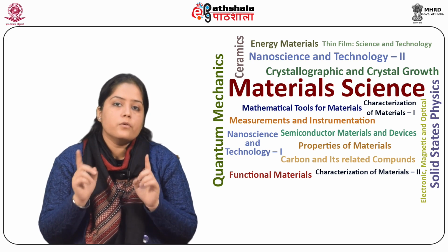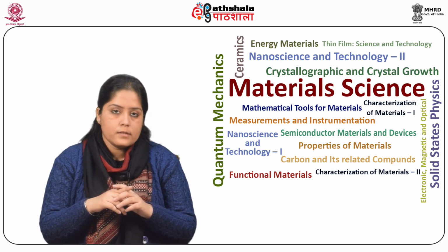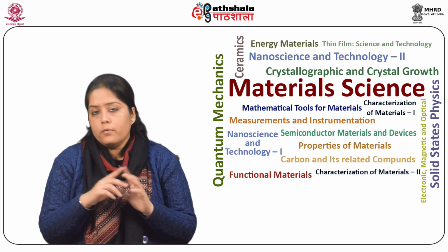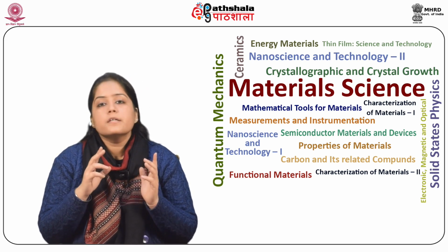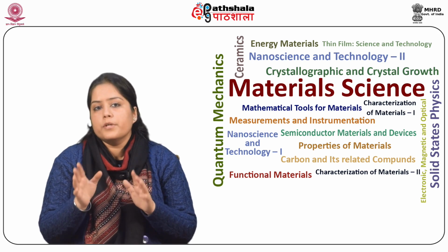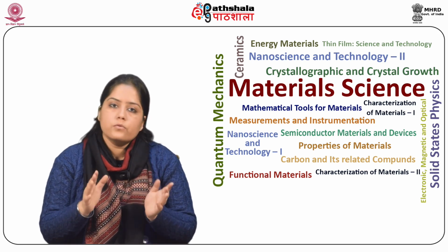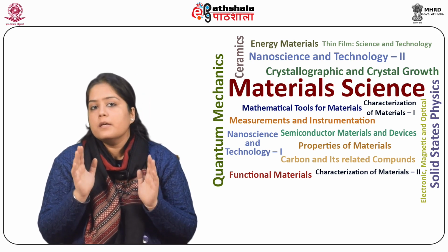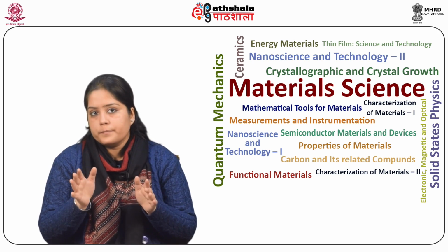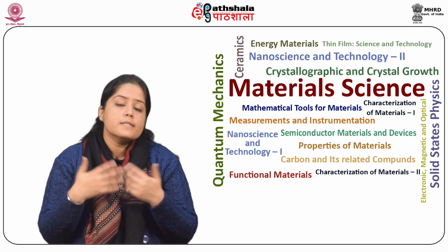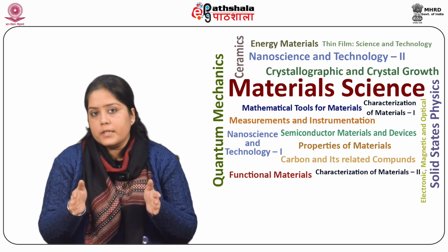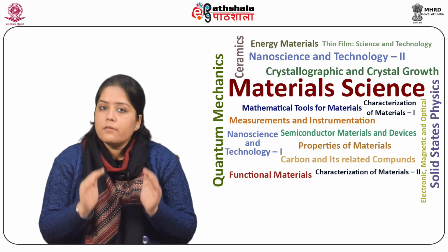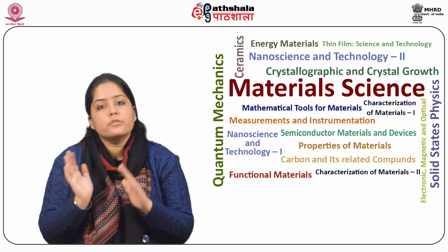The alloyed uranium such as U-Mo, U-zirconium, and U-Pu-zirconium fuels was used in EBR-I, which showed significant improvement in dimensional stability under irradiation and corrosion resistance.